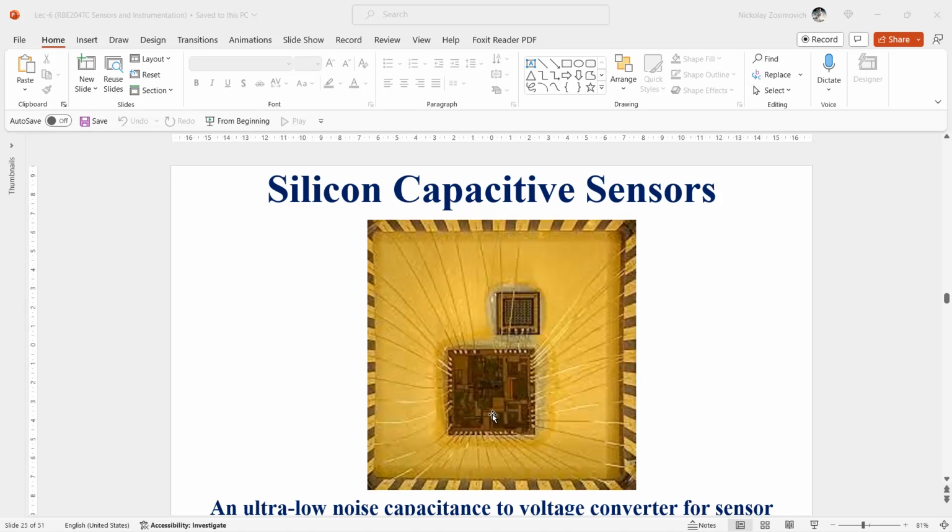The surfaces of the various parts making up a capacitance should be provided with a conducting layer acting as one of the capacitor's plates. Moreover, the spacing between the plates should be made small to obtain a reasonable capacitance and sensitivity. And the alignment of the two electrodes is also a critical processing step.